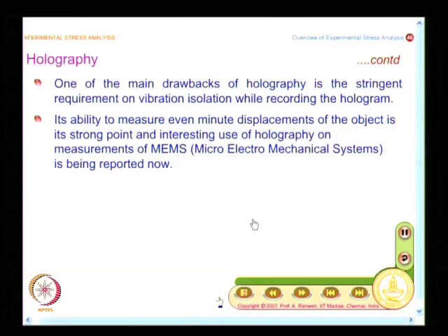We looked at what is holography, and we focus more on holographic interferometry, because holographic interferometry is necessary for you to make the displacement measurement, and we graduate from planar surfaces to 3-dimensional objects. But when we graduate, there is also a difficulty comes across, because I record more information, data interpretation becomes more challenging. But for simple planar surfaces, it is possible for you to do the data interpretation by appropriately constraining the model and also looking at the way the model is loaded.